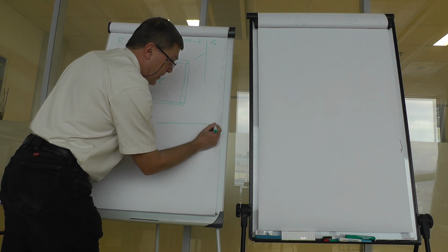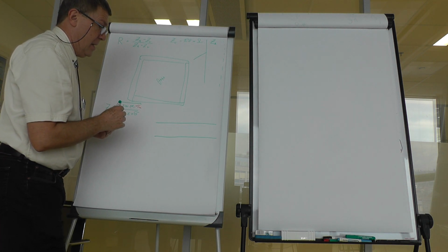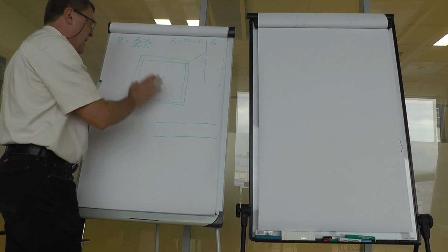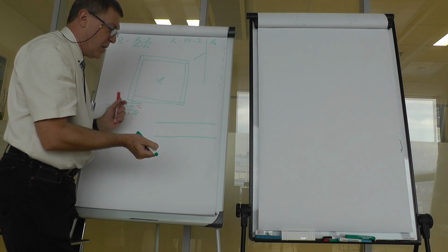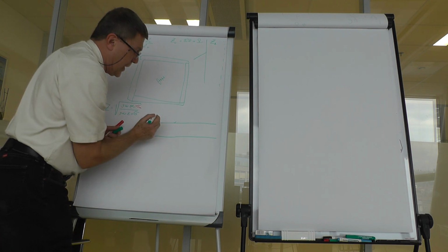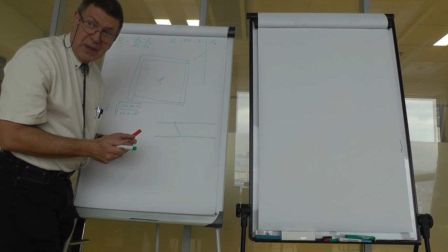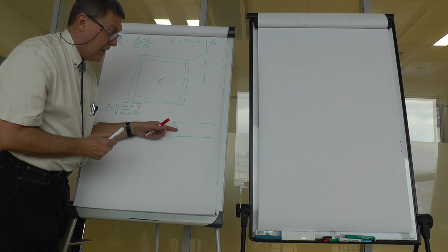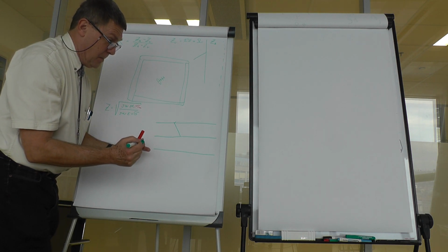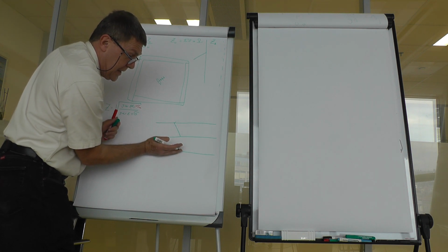So that the first layer has some small losses, but it has mostly the same impedance and mostly the same propagation constant, like the free space. So there is some very small reflection, but most of the wave gets inside. But yes, it is not very much damped, because that material is not very much lossy. But after all, there is a second layer, which is a little bit more lossy. And yes, there is a reflection at the boundary from the first to the second material.